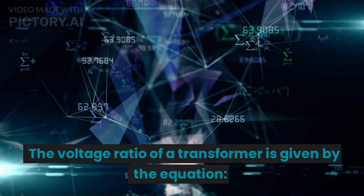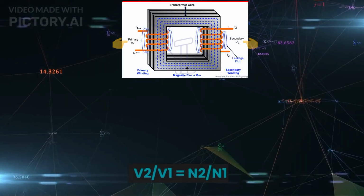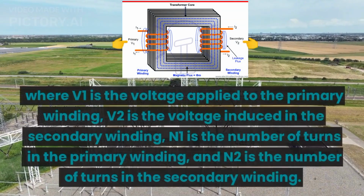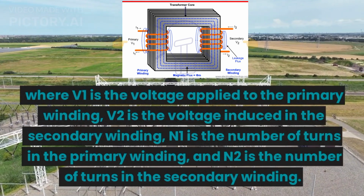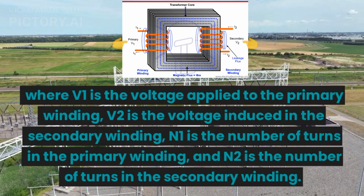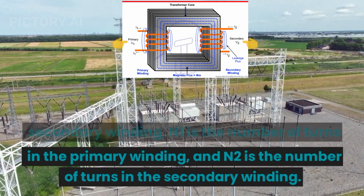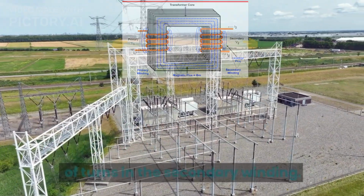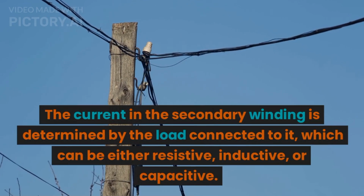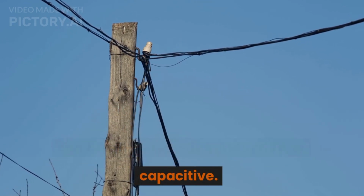The voltage ratio of a transformer is given by the equation V2/V1 = N2/N1, where V1 is the voltage applied to the primary winding, V2 is the voltage induced in the secondary winding, N1 is the number of turns in the primary winding, and N2 is the number of turns in the secondary winding. The current in the secondary winding is determined by the load connected to it, which can be either resistive, inductive, or capacitive.